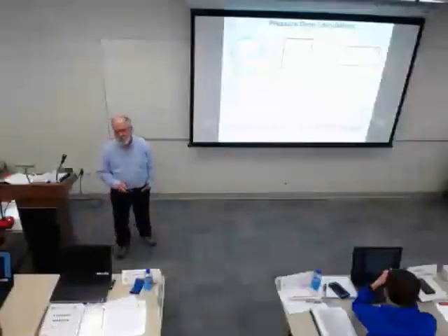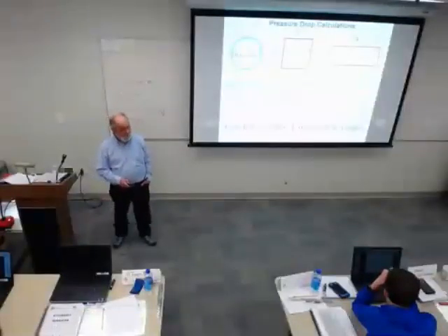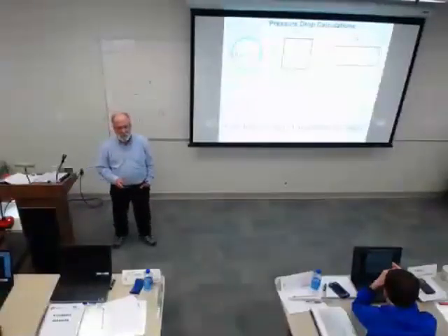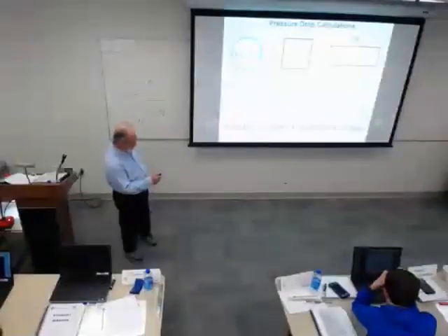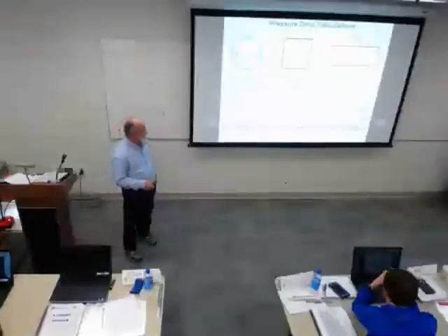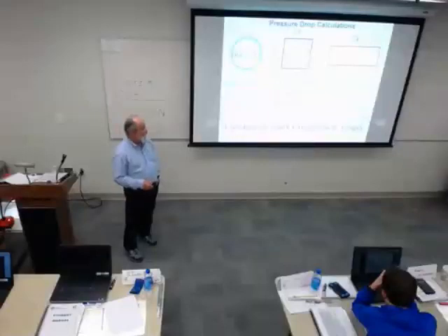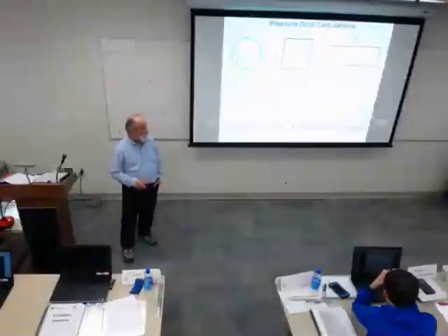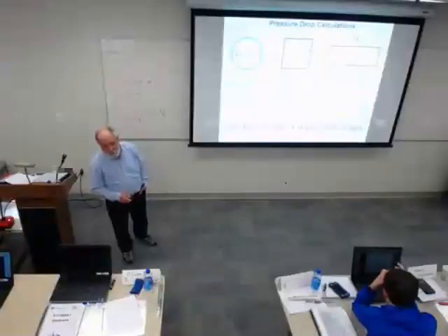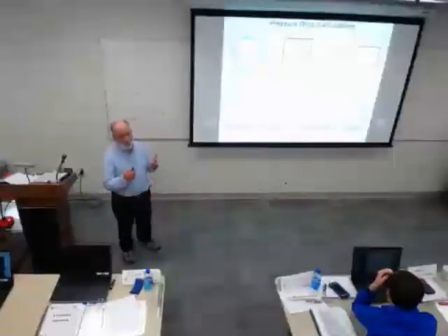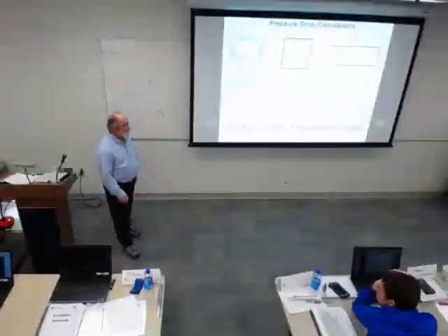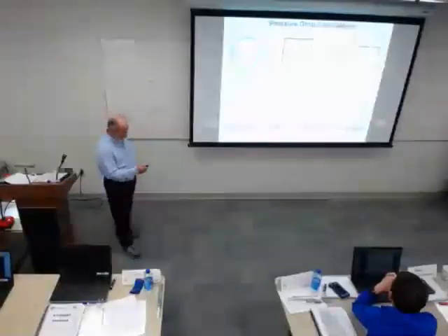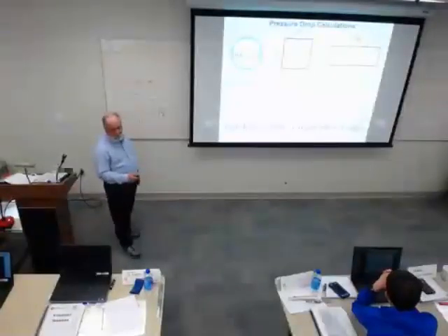In real life, round is cool, but you have to have really good agreements with the architect for the ceiling space and a lot of other things. So generally what you'll see is either square or rectangular. And typically, you won't see anybody getting out of a ratio of 1 to 3. This is 1 to 4. The reason is that if you are concerned about space, when you start going beyond that, you have to do so much to reinforce the duct that you start losing what you're trying to gain. So you won't see that go out that much. You will see some 1 to 4s, but not a lot.